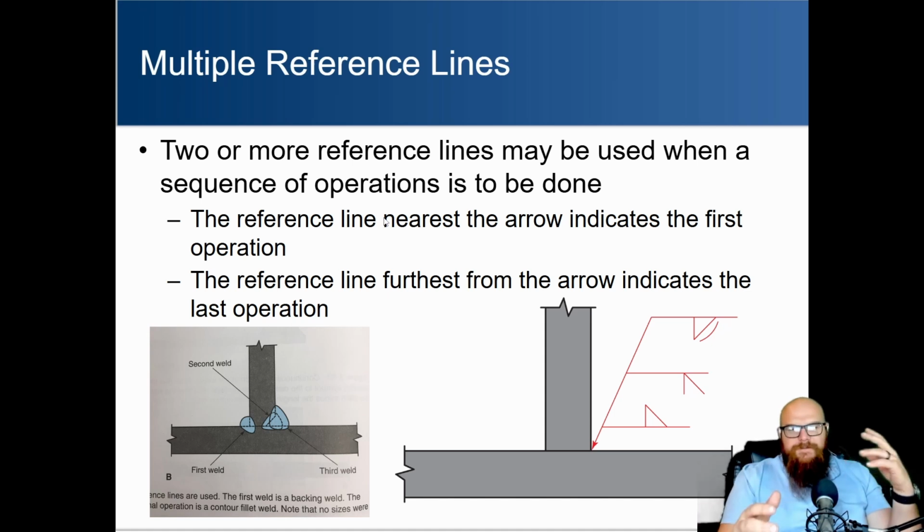You can also use welding symbols to indicate multiple welds. So if you've gotten to the triple pass on shielded metal arc welding, you know that we make 3 welds onto one side, and that helps to build up, especially on thicker metal. We might make more than one pass, and we can indicate this with weld symbols by having multiple reference lines from one arrow side.